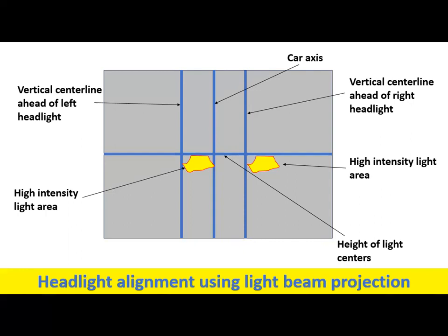With the headlights on high beam, the center of the light beam should be at the specified location on the wall. The amount of headlight beam drop may be specified by state or other regulations. Rotate the headlight aiming screws as necessary to place the light beams at the specified location.